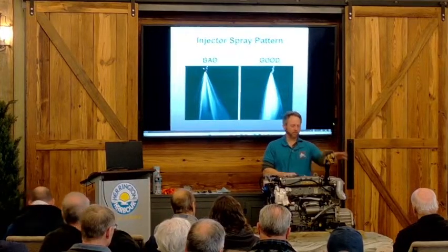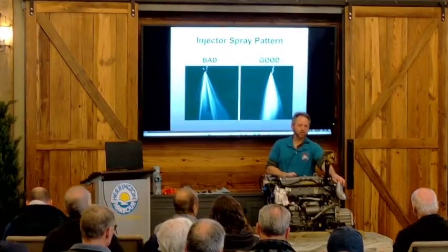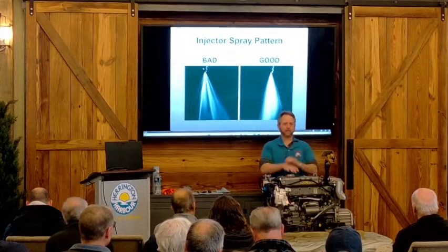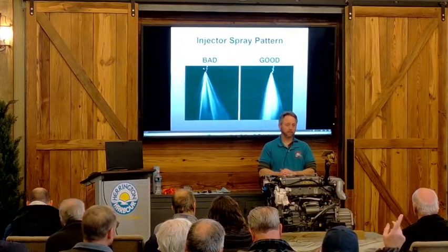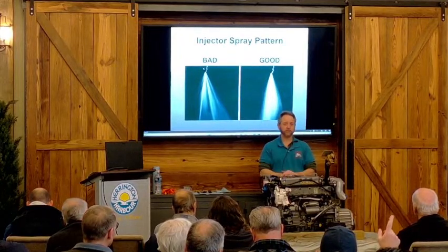It can cause your mixing elbows to clog up quicker and your injector tips to get more carbon on them, because you're not going to get a complete burn since you don't have enough oxygen because of the amount of heat.